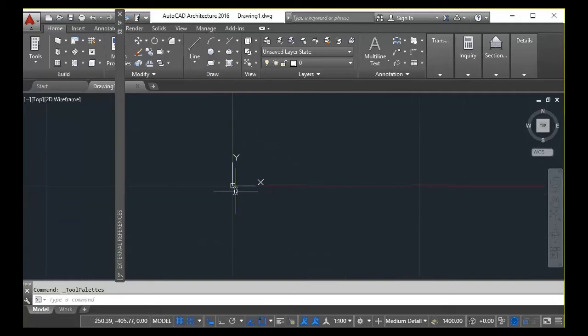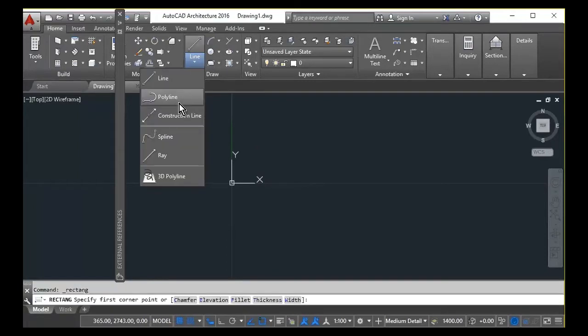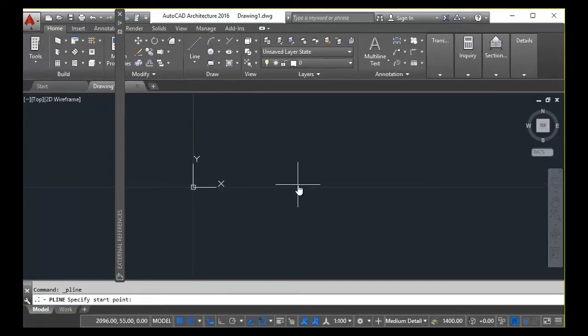Okay, so to get your floorboards, we're going to be creating the profile for the floorboards, extruding it, and using the array command to get multiple copies. First thing we want to do is create the profile of the floorboards, which is basically the cross section. We're going to assume that the floorboards are going to be 1 inch tall and 4 inches long.